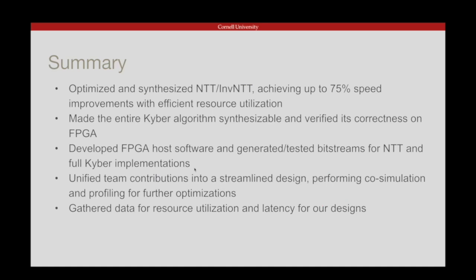In this project, we focused on FPGA acceleration of Crystals-Kyber, a quantum-resistant cryptography algorithm driven by the growing threat quantum computing poses to traditional cryptography. We implemented and evaluated 2 FPGA designs, a full Kyber implementation and an NTT-only implementation. In the process, we made the entire Kyber algorithm synthesizable, verified its correctness on an FPGA board, and developed FPGA host software to generate and test bitstreams for both designs.